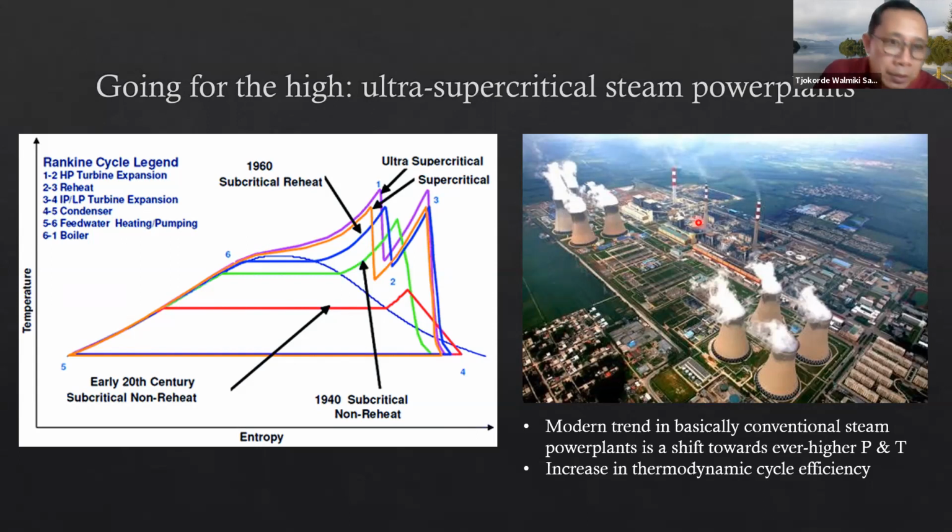because you have higher pressure, means higher risk, right? Higher risk of boiler explosion. As you go further high in boiler pressure and temperature, then your boiler system will be more prone to corrosion problems, right? And that means you need to add more chemicals to your water, to prevent the corrosion.